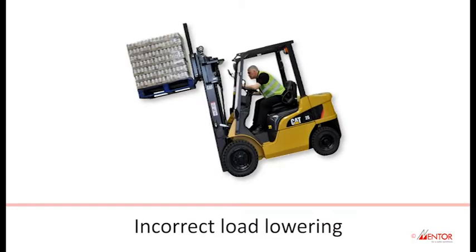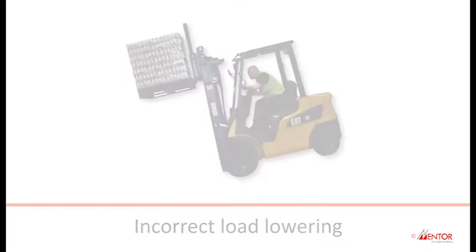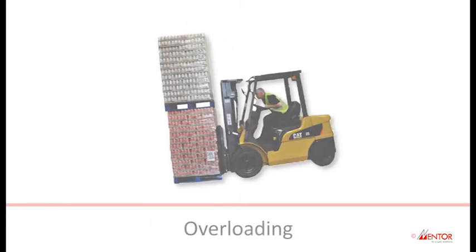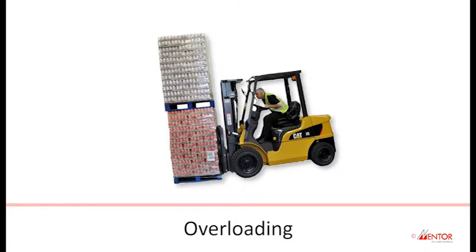Incorrect load lowering, for example lowering a heavy load, then quickly bringing it to a stop. Incorrect use of tilt, for example increased tilt at height. And finally, overloading, where the weight of the load is too great for the capacity of the truck.